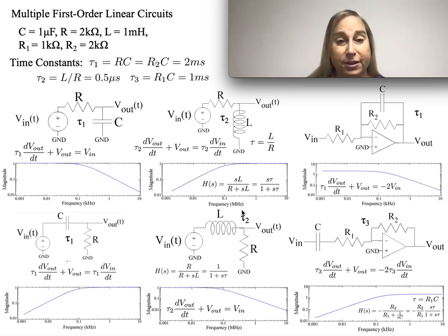The other way to look at this, in sort of a different time constant, is you could have done this in Laplace, and realizing that doing the Laplace version of the circuit, you get 1 over 1 plus s tau, which is what you expect for a low-pass kind of behavior. Interestingly enough, these two look very similar, which gives you a case where at high frequencies everything goes through. At low frequencies it gets attenuated and it's decreased, it's smaller, it's a lower level.